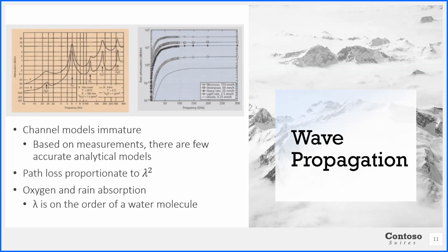The figure shows the power attenuation, which is on the y-axis here. The higher it is, the worse the attenuation becomes. As for the x-axis, it indicates the frequency. The figure shows that the attenuation in the 60 gigahertz range is particularly high due to oxygen absorption, and in other cases shows water or rain peaks.